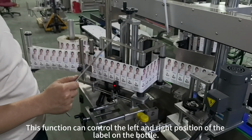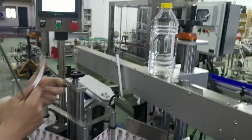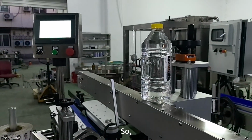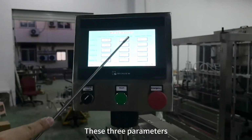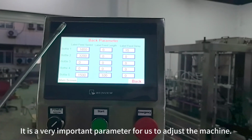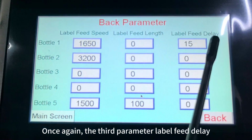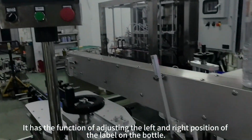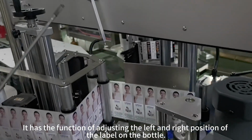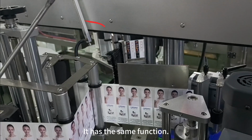This function can control the left and right position of the label on the bottle. So, these 3 parameters are very important for us to adjust the machine. Once again, the third parameter, label feed delay, has the function of adjusting the left and right positions of the label on the bottle. The position of the label on the bottle can be adjusted by moving the sensor left and right. It has the same function.